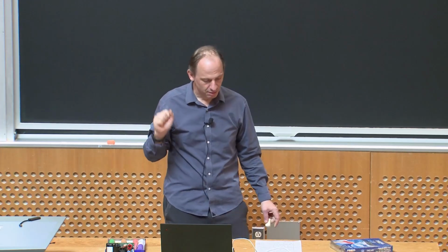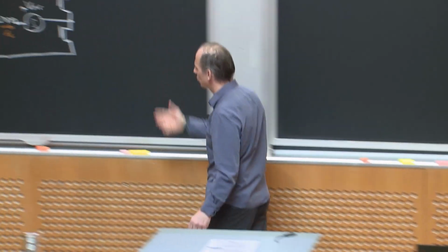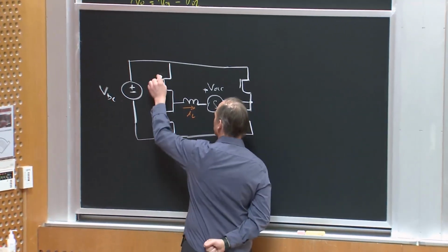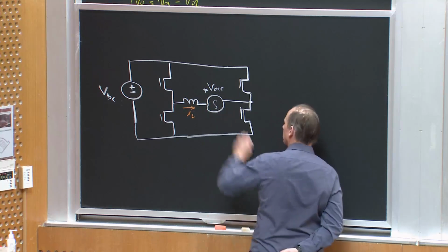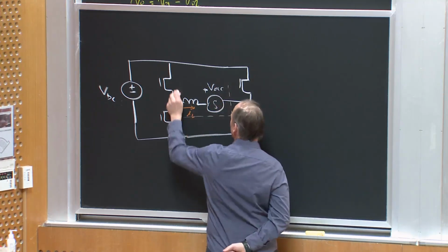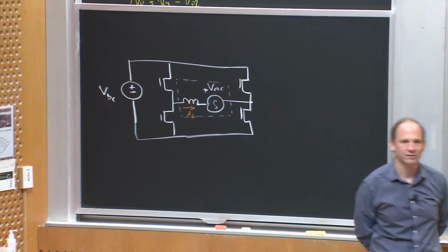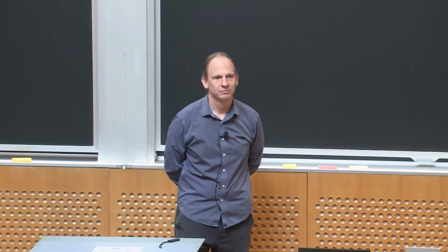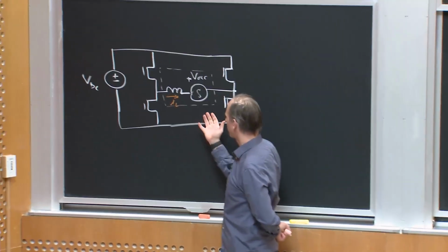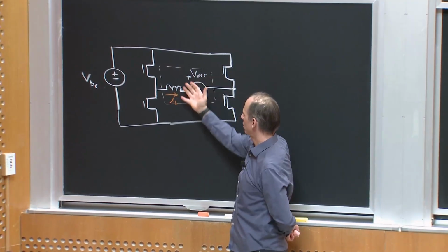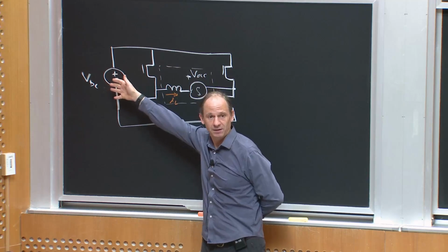And in fact, people often do this. Where might you do this? Well, imagine for a second that this whole box is the back EMF and winding of a generator. I can then extract energy from the generator. There's a mechanical input in, it generates a back EMF voltage, and I take power out to the DC side.